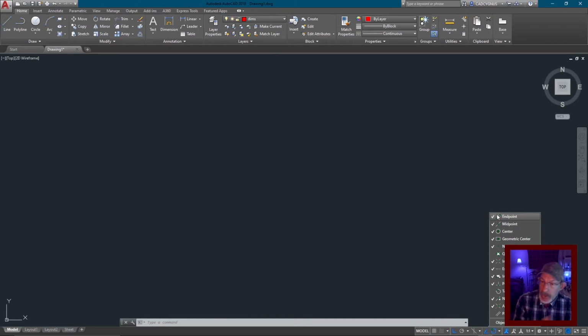So if you're showing me something on a screen share or another video, we can be on the same page. And that's very, very important, especially when you're drafting, drawing, piping, HVAC, architectural building, designing for interior, whatever. Okay. Endpoint, on. Midpoint, on, center, on. And what I mean by on, you can click them on or off with the check mark. Geometric center, on. Node, on.